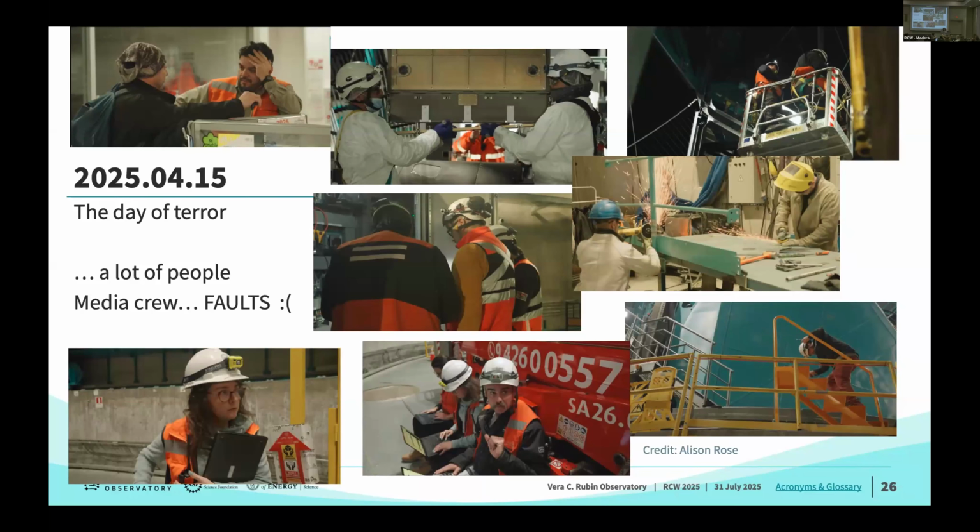Then, doing these dome tests days before, we blew some switches, so we needed to change them also. And there you can see the electrical team changing the switches. We also needed to take out a part of the fence from the telescope itself, which is in this picture here. But when you take anything out of the telescope, that means you're changing the mass, and if you change the mass, you need to balance the telescope again.